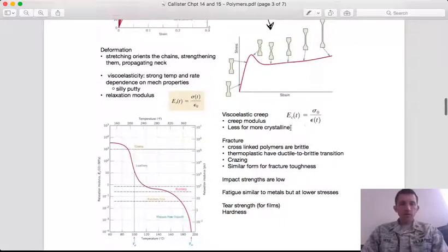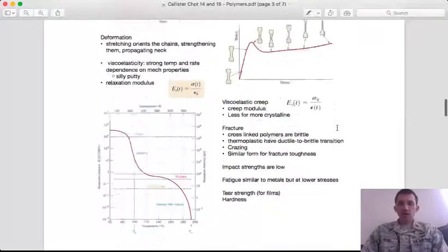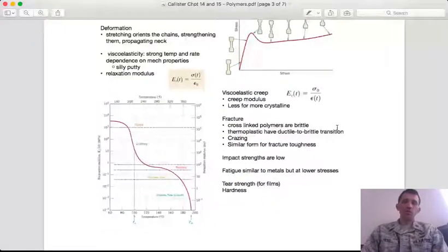Here, instead of a relaxation modulus, we kind of think of this as a creep modulus, in the sense that if you remember back to our discussion of creep when we talked about metals, remember creep happened when we had a sustained load at high temperatures, and the high temperatures kind of creates the mobility for, say, a metal alloy that you may have in a polymer system at ambient temperature or much lower temperature, in the sense that you have a balance between strain and recovery, and so you see sort of a constant increase in the strain over a sustained load.